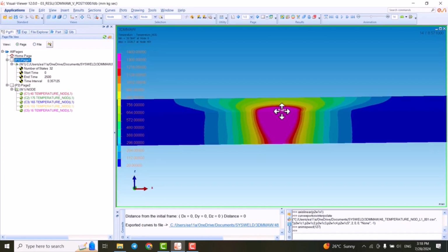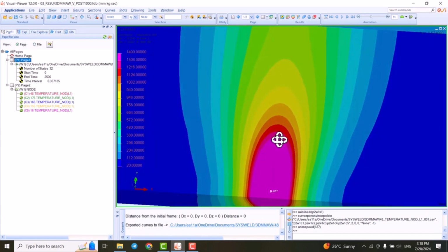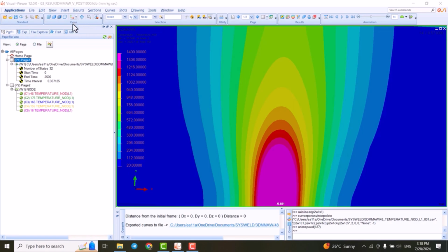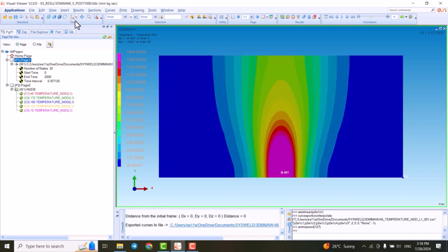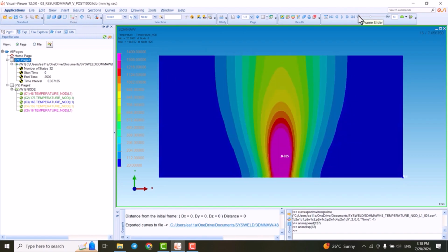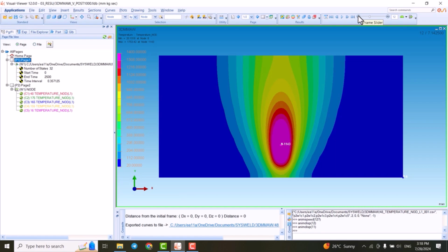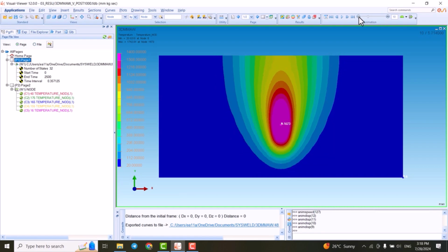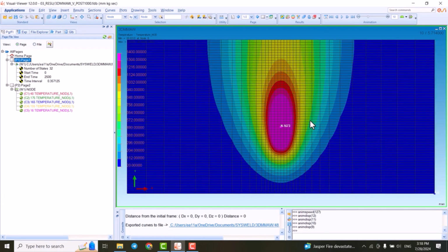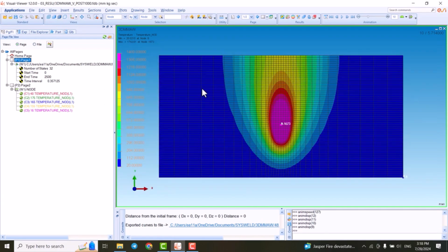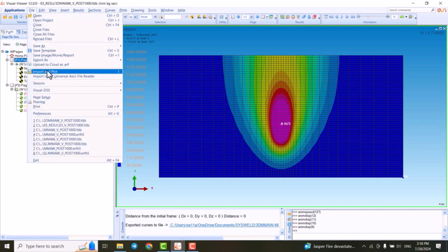We can come back to page 1 and see what happens if we want to go from a path and plot our results in a path. So we go to the top view, and we can say, let's say here, which is in the middle. So we select this one, as we can see the nodes on the mesh here. So once more we go to import and plot,